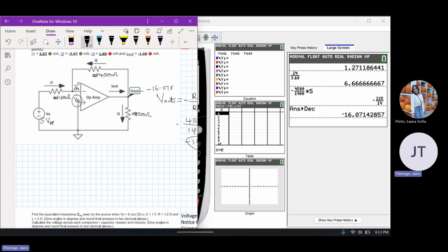The current I2 and I1, since the current here is 0, and the direction of I1 is into the op-amp via the negative terminal, the feedback current, or rather the current via the feedback resistor, is also meeting at this node. And the current given here is 0. One of our golden rules. We'll have I1 plus I2 be 0. So that's our first equation.